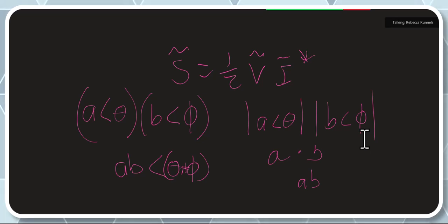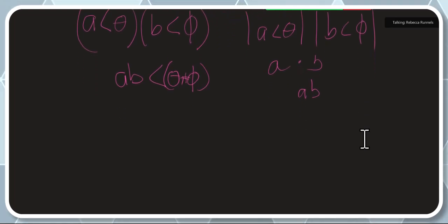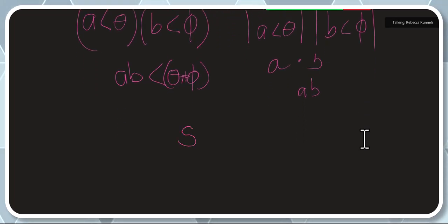And so I get the magnitude. Whenever you have a formula that has the complex part, if you just use just the magnitudes all the way across, you're still going to have a true formula. So it is still true that apparent power, not just the magnitude of it, equals 1/2 the magnitude of the voltage times the magnitude of the current. That is still also true.